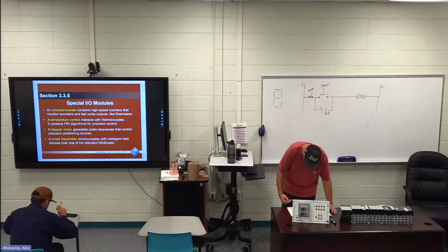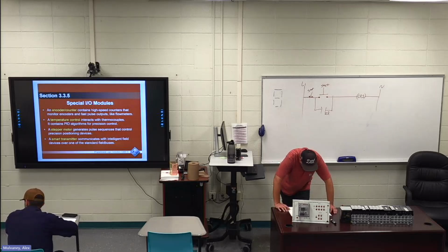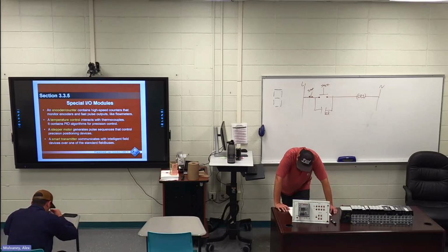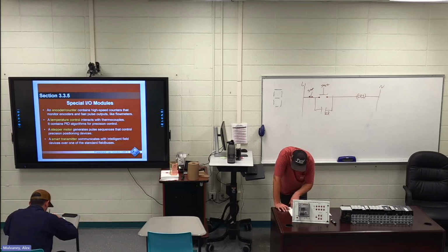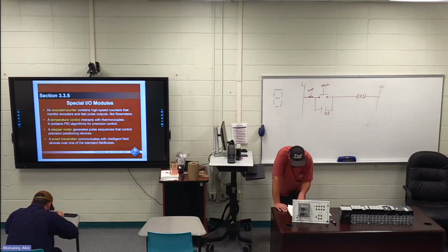Special modules, whole paragraphs highlighted. While discrete, numerical and analog modules handle the majority of PLC interfacing needs, there are occasions when specialized devices may need to be connected. Examples include high-speed encoder counters, servo controls, stepper motor controls, synchronized access controls, velocity control, temperature monitoring controls, and smart transmitters. I guess the encoders aren't part of the numerical interface modules. Read back through there, but it's just a multi-bit thing.